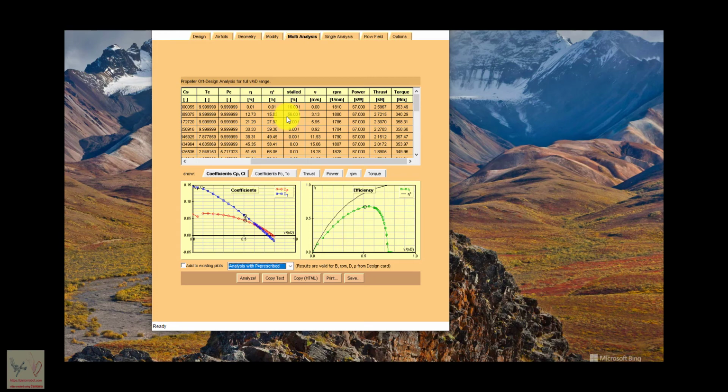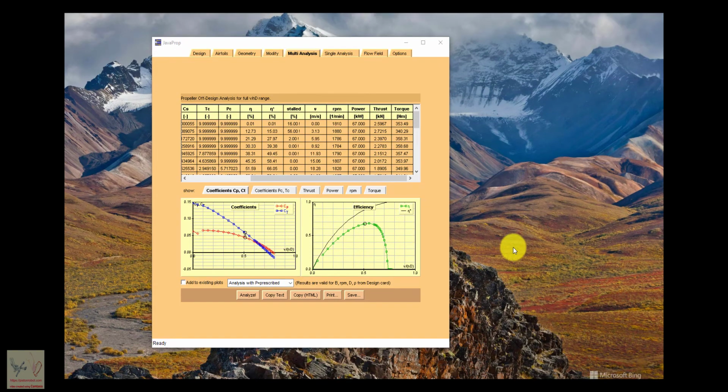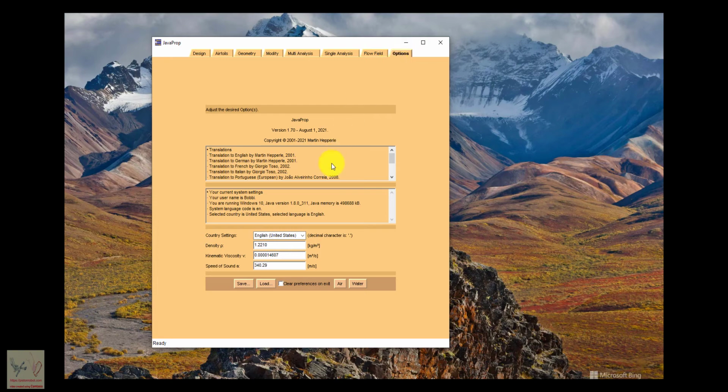That's total weight. That's the drone weight plus the fuel weight plus the payload weight. We're putting in 50 gallons of fuel, which is 335 pounds of weight. There are a lot of considerations. One thing that's important to realize, in essence, because of the ratio of the height of the drone to the diameter of the Earth, the weight of the drone isn't going to change at any altitude that we care about, but the density of air changes.